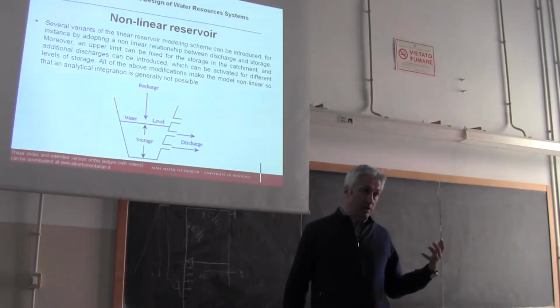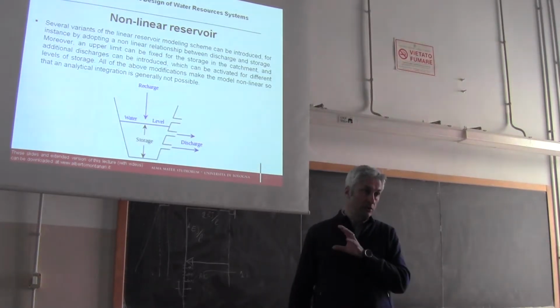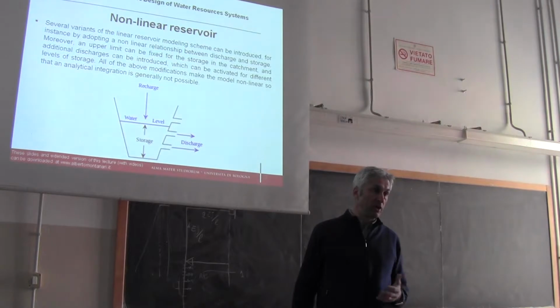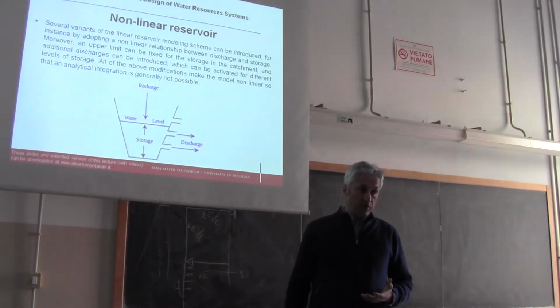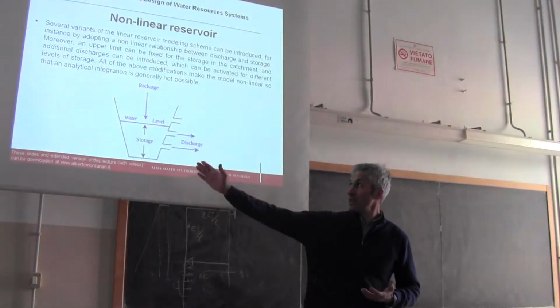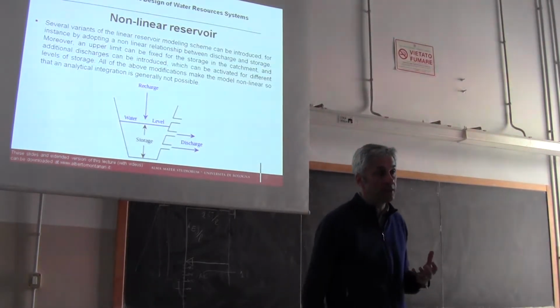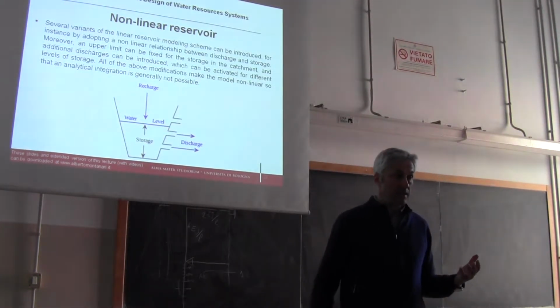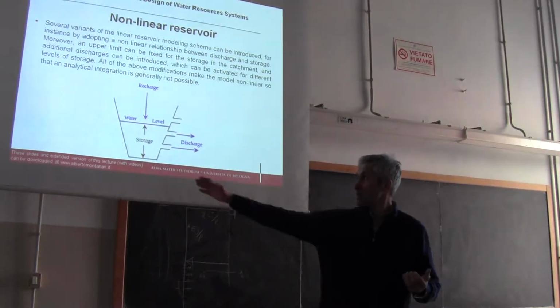This is a reasonable assumption. It's in principle easy to introduce these additional flows in the same way you can introduce evapotranspiration. The only problem is that the model becomes non-linear. Even in this case, you see that if you introduce additional flows, additional discharges that are activated when the storage